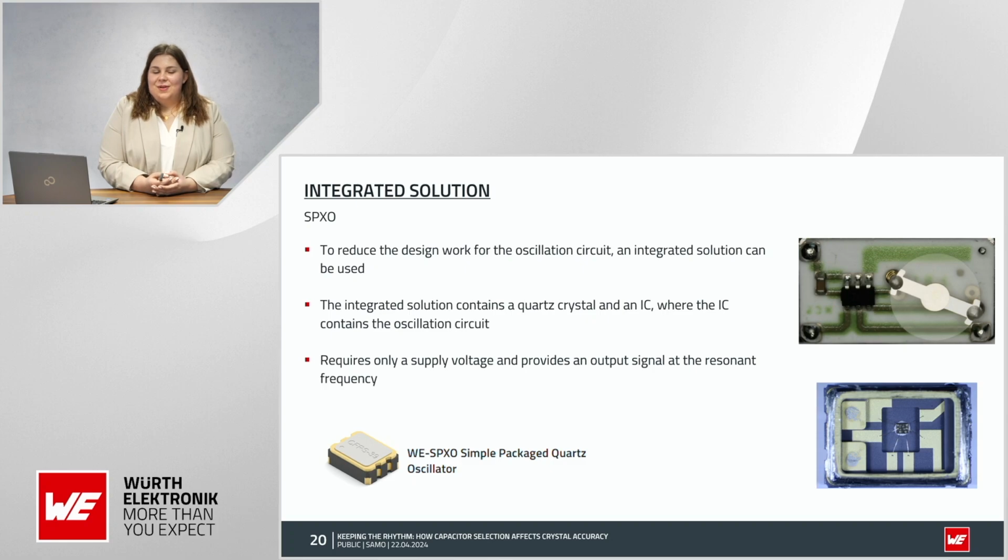Then we come to a small outlook, because what we talked about is a lot of design work to make sure that you really achieve the accuracy you want. And a lot can go wrong because we can easily affect the frequency. But what if we don't want that? What if we want an easier solution where we don't have so much design work? Then we can recommend an SPXO, a clock oscillator.